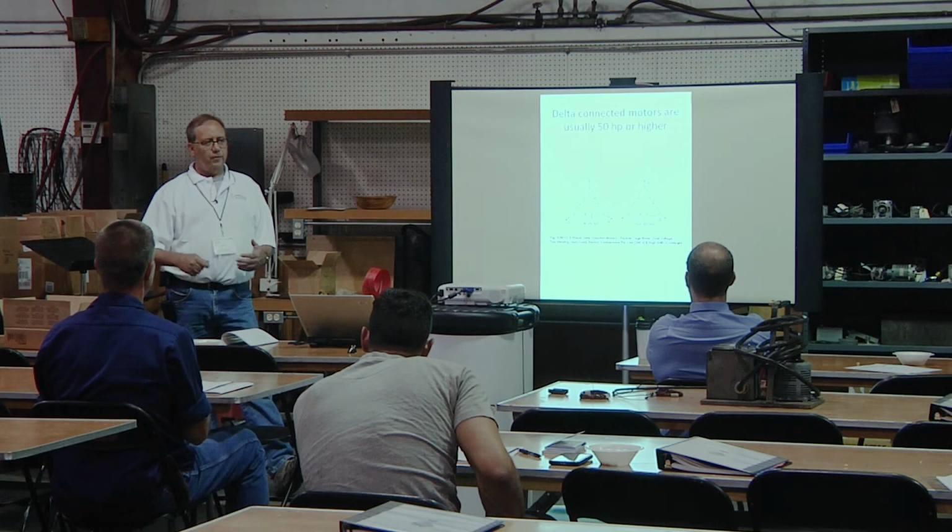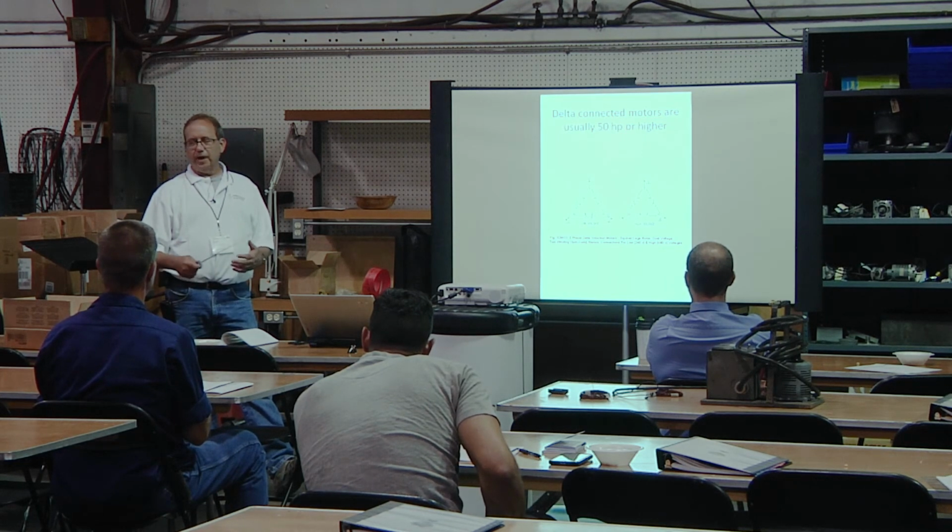So they'll find somewhere in the middle and design the winding for like 250. Put 277 on it, it'll be all right. At 480, they're going to be overvolting it a little bit, yeah, it'll be all right, that kind of thing.